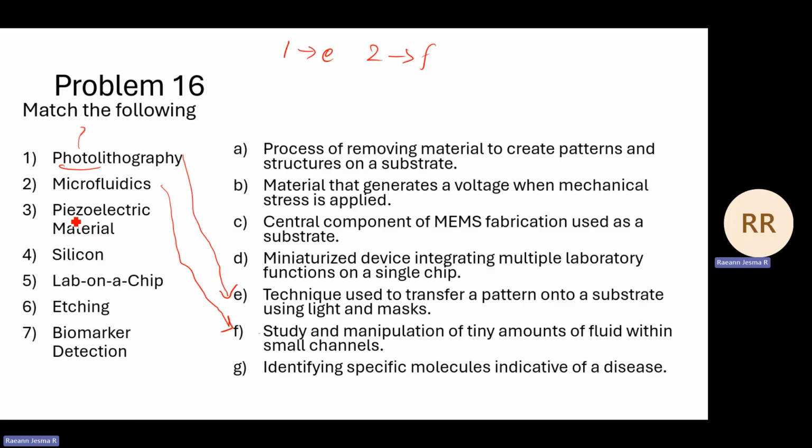What is a piezoelectric material? A piezoelectric material is something that will generate some voltage when mechanical stress is applied. So that is option B. These kinds of piezoelectric materials are generally non-centrosymmetric. They should have this non-centrosymmetric property. Only then, when we apply some sort of mechanical force to the material, will we get some sort of voltage. Otherwise, we will not have this kind of effect.